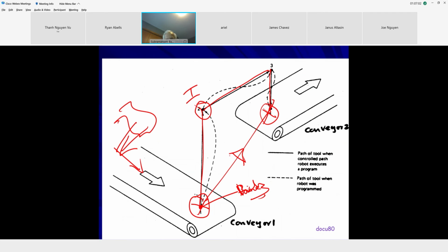How am I going to program? Well, you go to this position and let the robot know the pitch, the roll, and the yaw, either through a simulation model or through moving manually and recording the position. Then I am not going to exactly move along this line. I'm just going to go manually, and I know the target position is this intermediate.